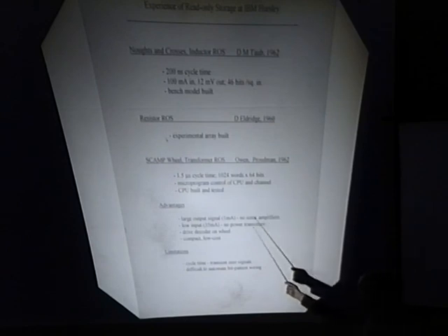The outstanding advantage of it is that a 1 milliamp signal was produced, which is large enough to set a sense latch directly. The input power was 35 milliamps, which was what could be obtained from a logic circuit. So we can say, put in a nutshell, this is a memory with no drivers and no sense amplifiers. There really was no other technology to touch this that I'm aware of.